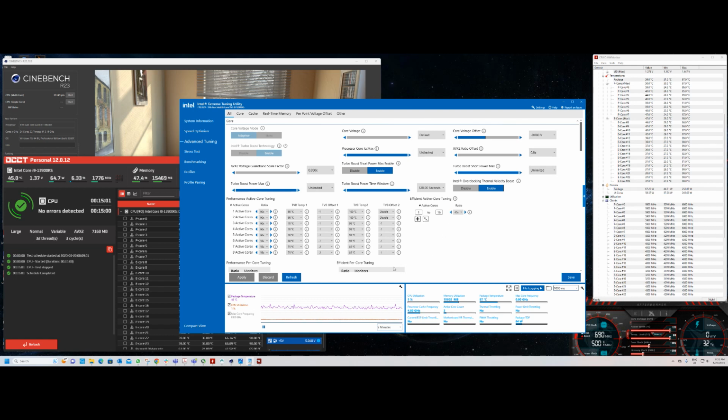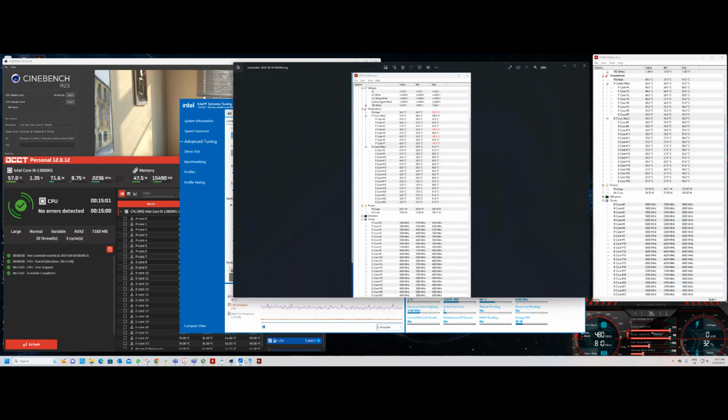One of my previous strategies, which I'm going to share with you guys, was using the AI overclocking, because my previous manual overclocking didn't go as well. There was a lot of thermal throttling going on, and I did experience some crashes like blue screens of death, like watchdog errors and things like that. I tested using Cinebench and a few others.